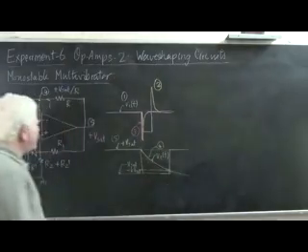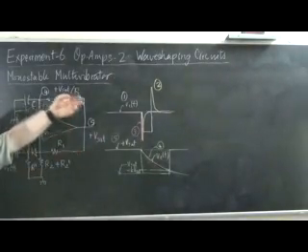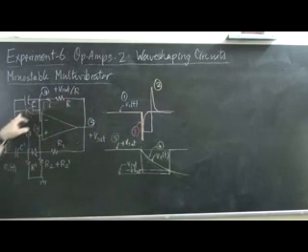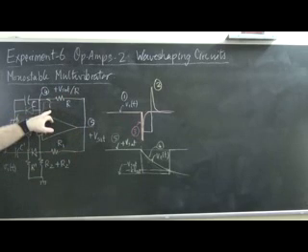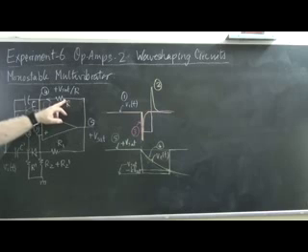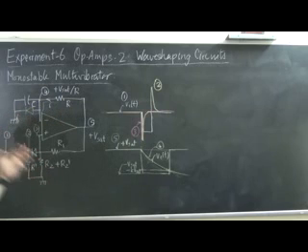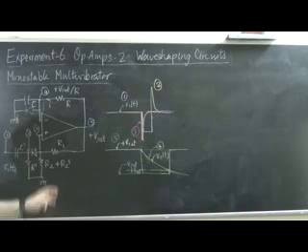and that point of time is where the op amp switches back to plus Vsat, the diode turns on once again, and the capacitor becomes deactivated, and a current steadily again flows of value equal to I, and passes through the resistor and the diode and goes into the ground. Now again the monostable will remain in this state indefinitely until another pulse is applied at the input.